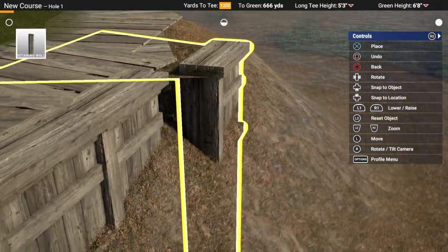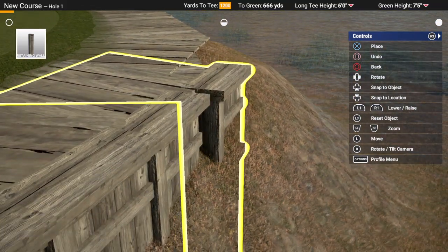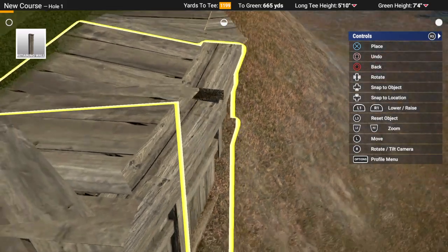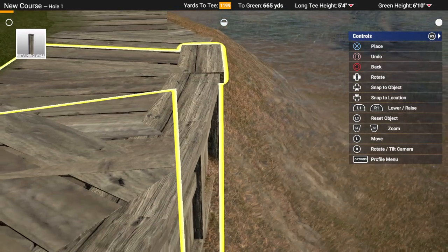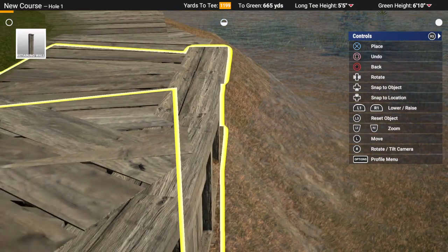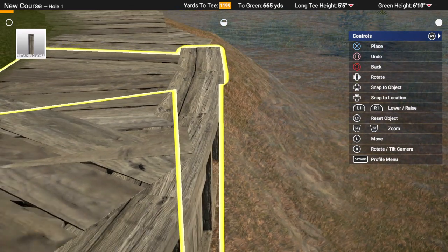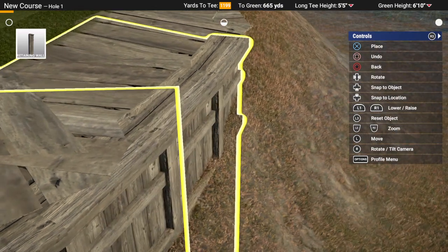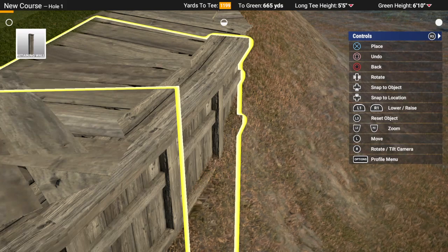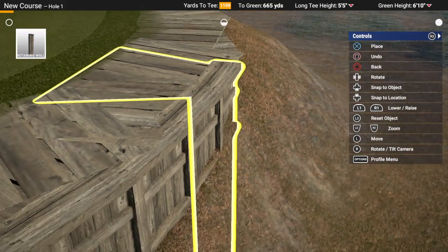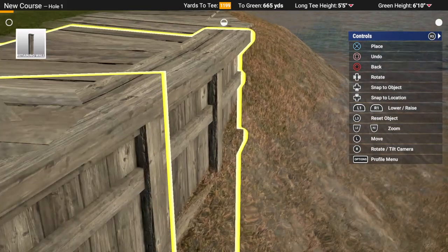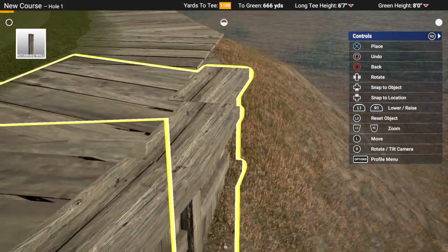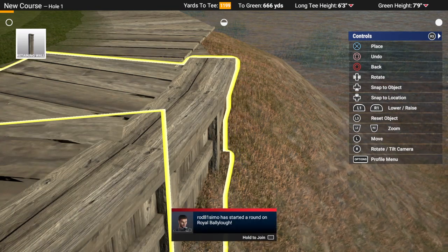And now you see, this is what I'm talking about with these edges. I'm going to back that one up. So when I'm sighting this in, I'm going to try to get the outside edge of the retaining wall to just barely clip the outside of that corner there. And that helps cover it up while still staying flush to the other piece, or at least as close to it as I can.